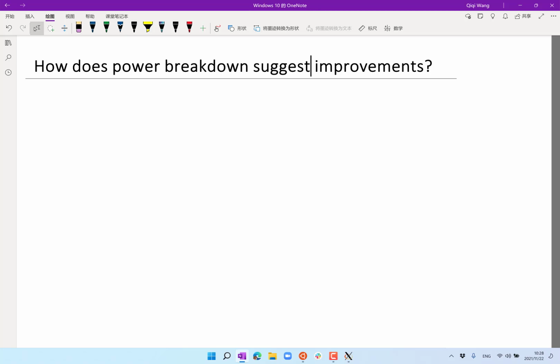Yes? You feel like going through the same amount of skin friction drag, but less induced drag? Maybe let me ask again. Without changing the span, so b is the same, but shrink your chord length. If you fix the span, how does the induced drag change as you shrink the chord length? Doesn't change, right? The induced drag is just a function of the span. So induced drag doesn't change.